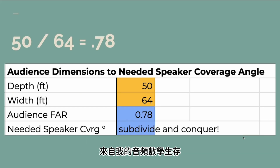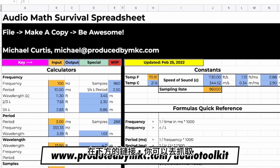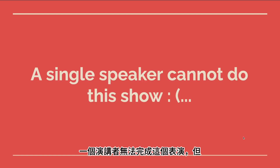What I want to introduce here is a section from my Audio Math Survival spreadsheet. Kyle's going to have the link below for us where you can go snag that, but it does that for you, and it creates an audience FAR of 0.78. Right below that, it should spit out the coverage angle of the best speaker in the world that would fit there. But instead of giving me an angle right now, it says subdivide and conquer, because it's actually not possible for a single speaker to get wide enough to fit perfectly to an audience that is wider than it is deep. So it says, hey, subdivide and conquer, a single speaker can't do this show.